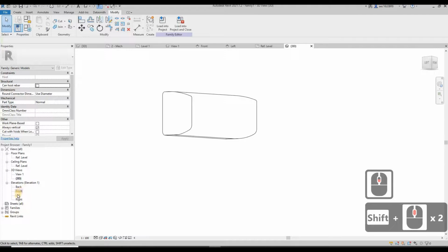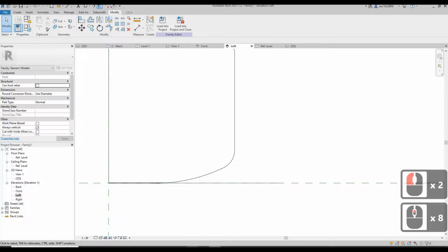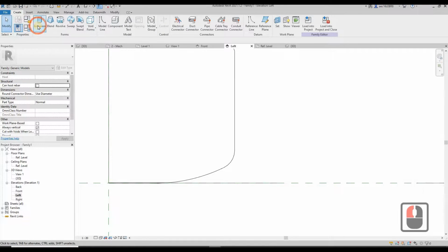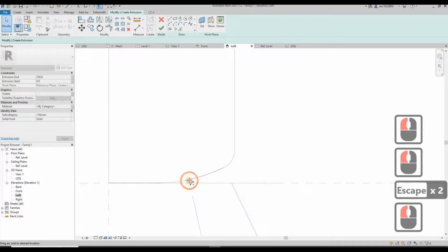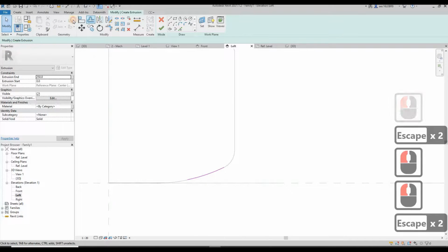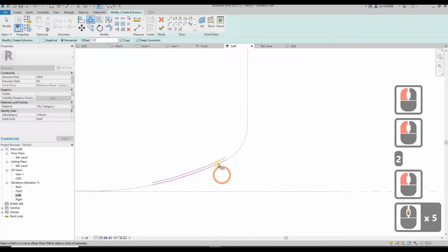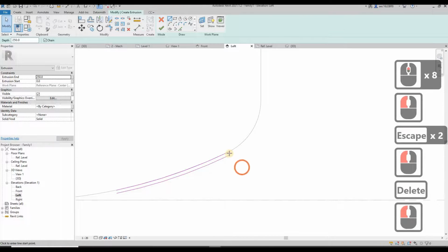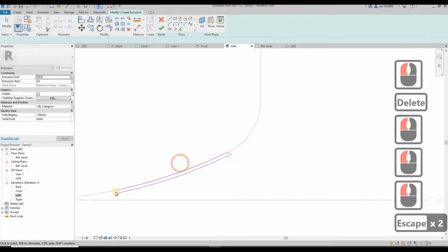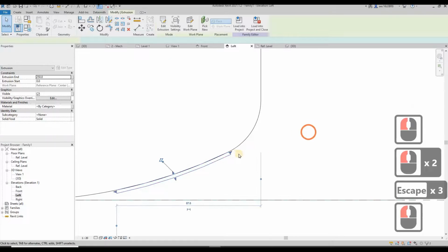Okay, then from the left view, I'm going to create another extrusion here for the aircon diffuser. Let's say I'm going to create the extrusion here. I'm going to pick this line somewhere like this. Then I'm going to adjust this line to here. Then I'm going to have a little bit offset, like 2 mm. Okay, maybe 2 mm bottom here. I just create an indicative shape of this diffuser. Okay, the flap, and finish.